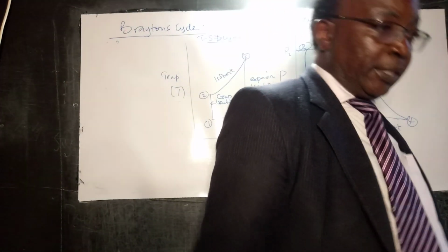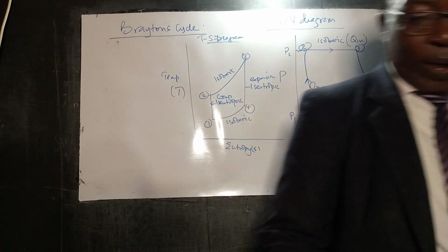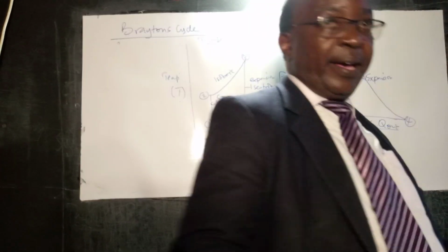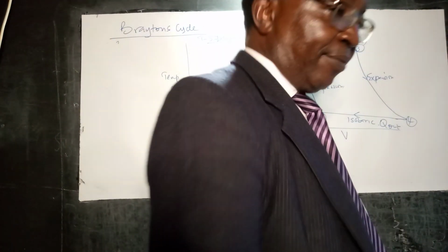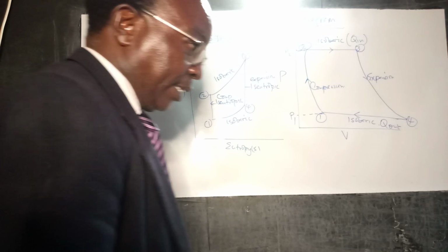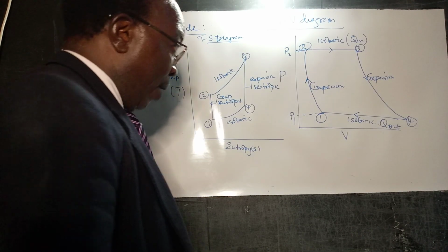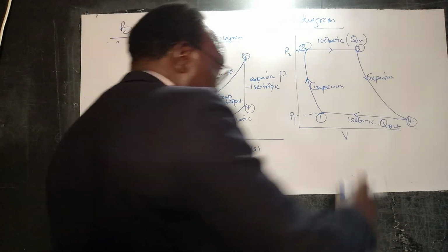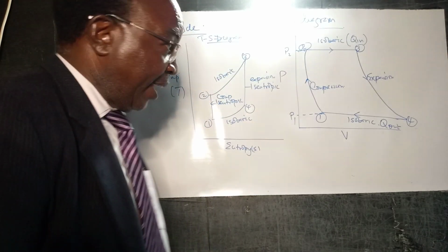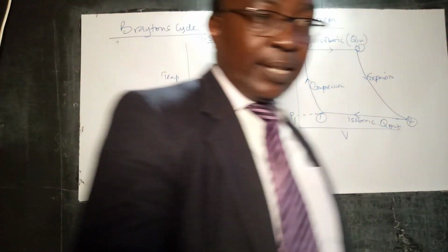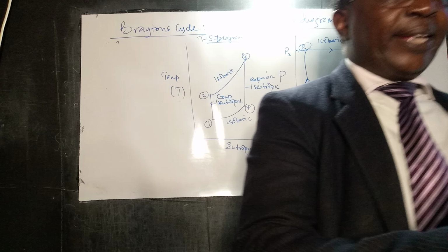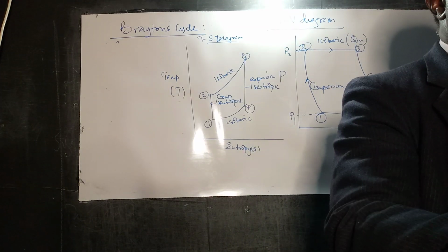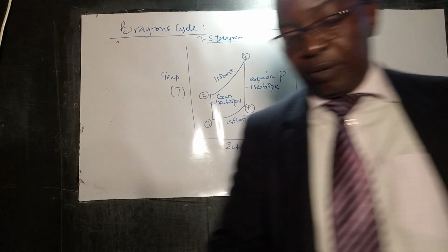Work is reciprocating. Remember, the piston rod is connected to the crankshaft, and so it will be reciprocating work. And then, of course, there's the rejection of heat in another heat exchanger. That one that I've described is referred to as a closed Brayton cycle.